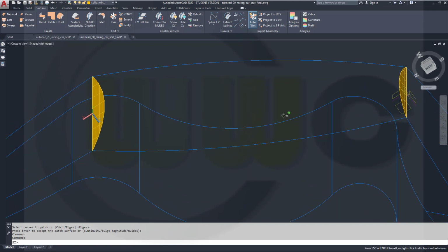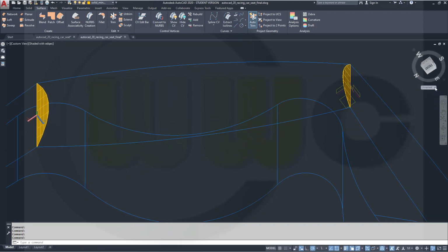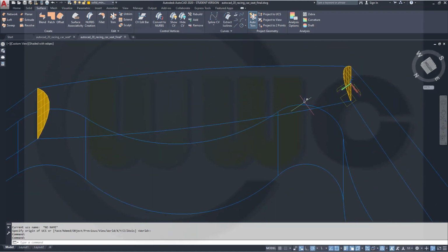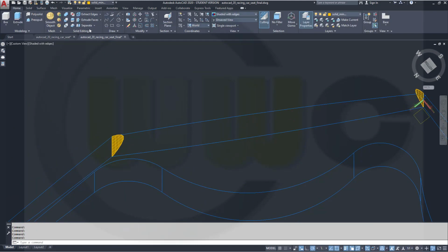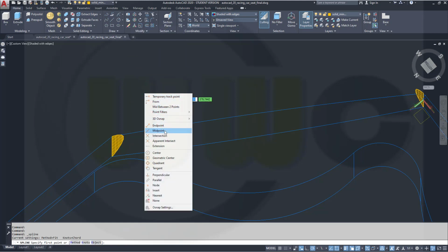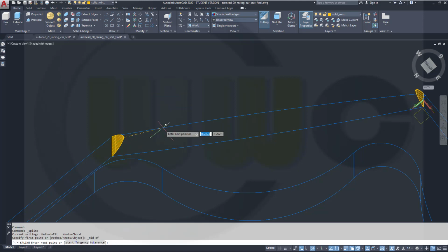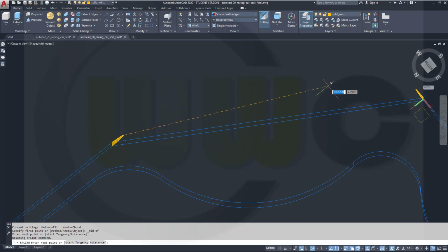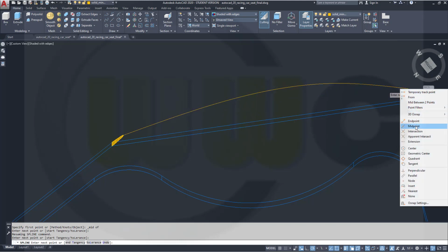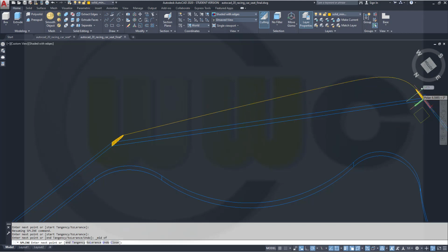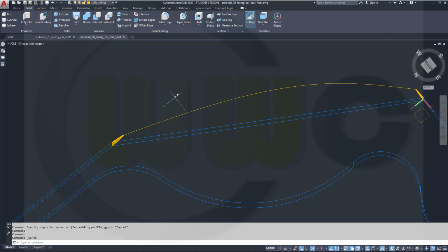Now let's take a look at my axis system. I want to go back to the world coordinate system, and then I could draw a spline. Yes, so go for home, go for a spline, right click, check the midpoint of this one, like that. Let's see, maybe it moves like this and then goes down here. Right click midpoint on this edge as well. Right click enter.